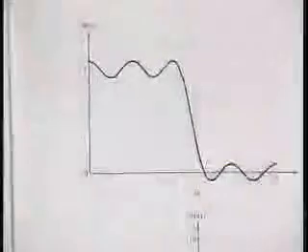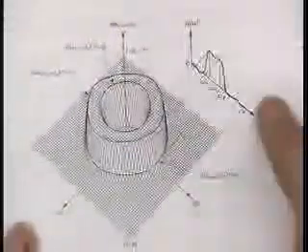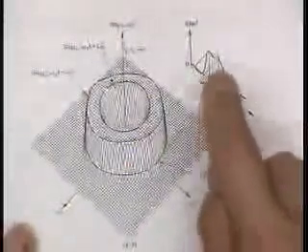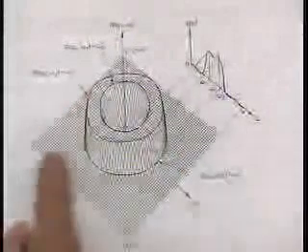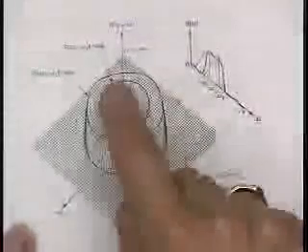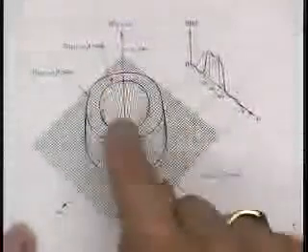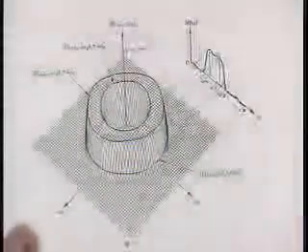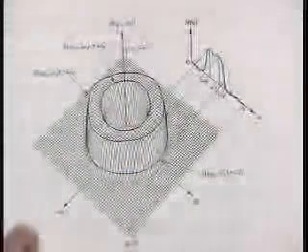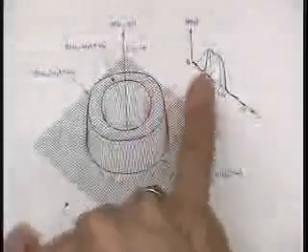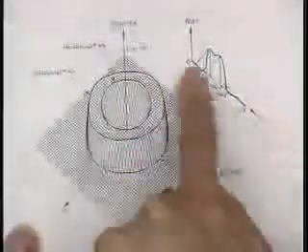If you remember from last time, you go to your H of omega, you pick a particular omega, let's say omega naught prime, and for all the contour points corresponding to cosine omega naught prime equals T of omega 1, omega 2, the height of this whole contour is equal to the height of H of omega at omega naught prime. So if you've come up with a T that's larger than 1, it would not correspond to any real values of omega between 0 and pi.